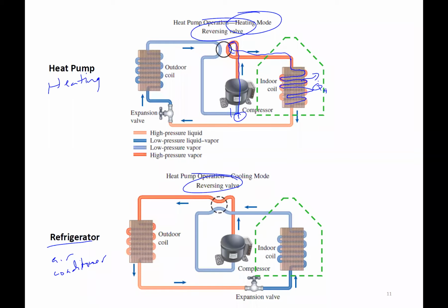So now we go through our condenser, we get to a saturated liquid, or around there, and then we go through our expansion valve, constant enthalpy, which drops its pressure, and drops its temperature significantly, okay? And we have our low temperature, we drop it low enough that now we can pull heat from the cold outdoors, okay?